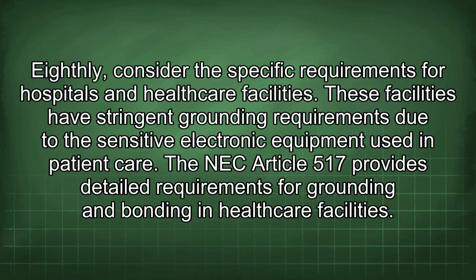Eighthly, consider the specific requirements for hospitals and healthcare facilities. These facilities have stringent grounding requirements due to the sensitive electronic equipment used in patient care. The NEC Article 517 provides detailed requirements for grounding and bonding in healthcare facilities.